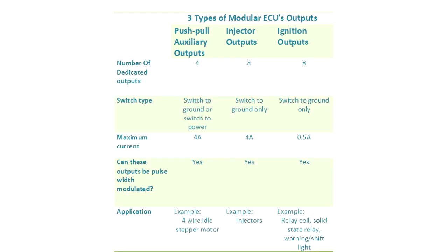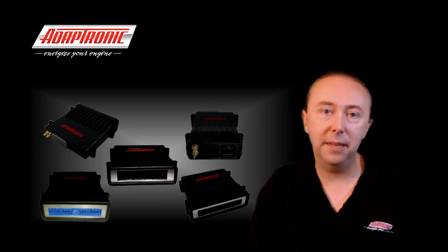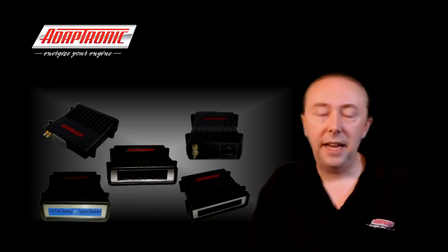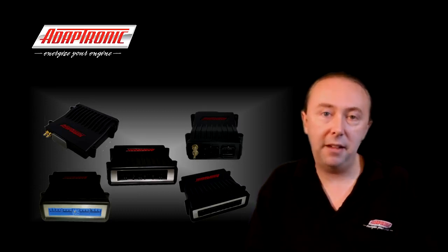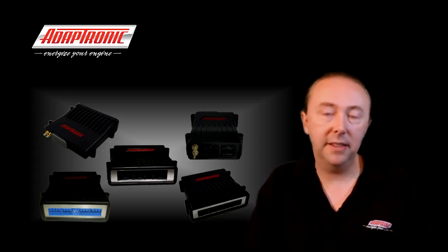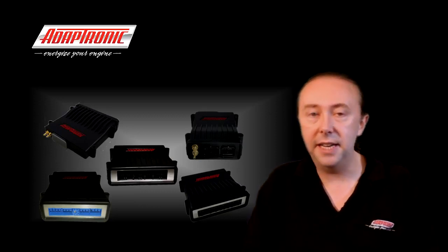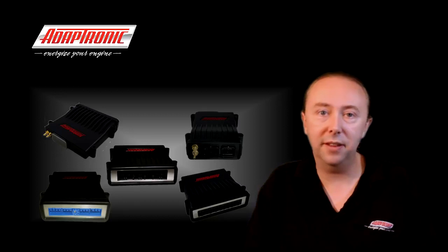The first is a push-pull auxiliary output, which can either switch to power or switch to ground. All four of the auxiliary outputs on the M2000 are of this type. Any load that requires being switched to power will need to use this sort of output, and this includes 4-wire stepper motors. So for example, if you want to run a 4-wire stepper motor on an unexpanded M2000 ECU, then you'll need to use all four auxiliary outputs to drive the stepper motor.